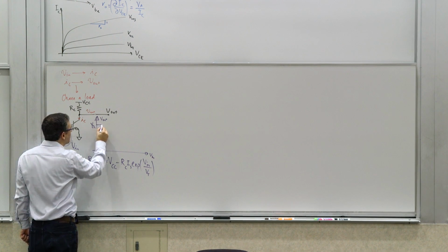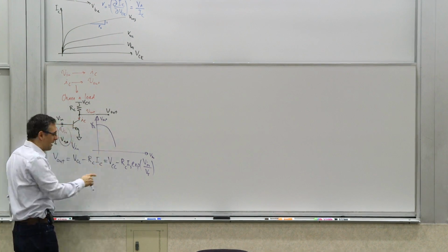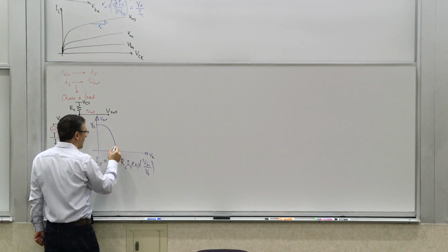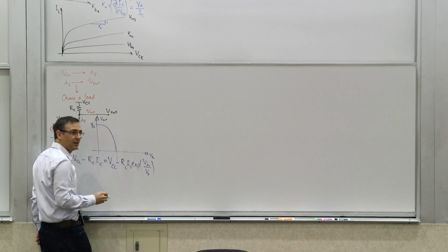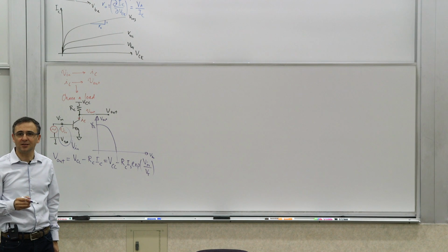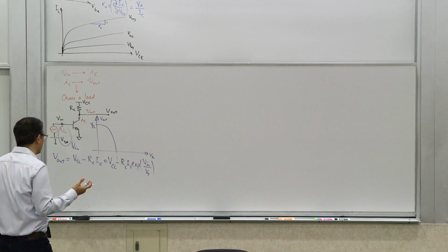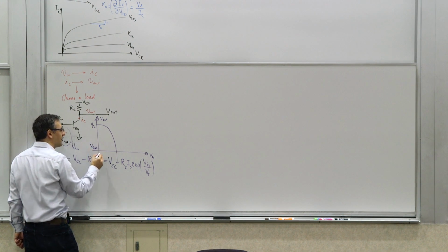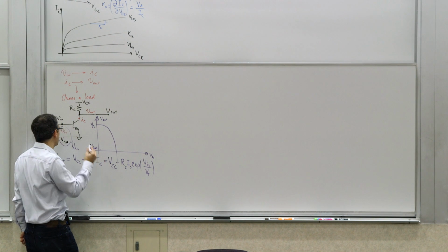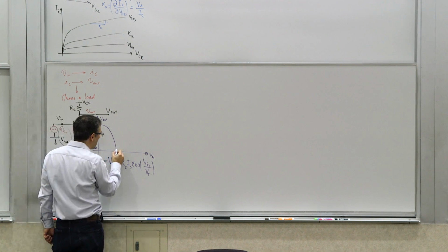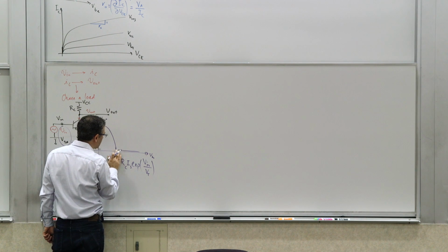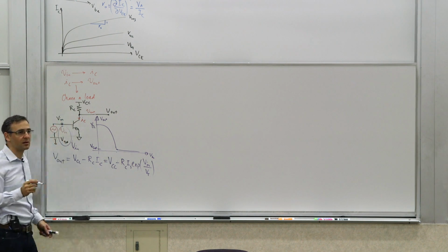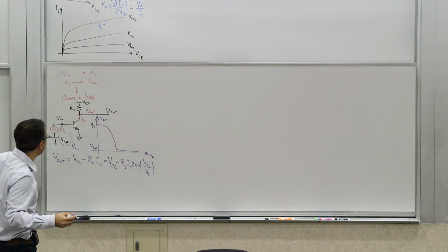As you increase Vin, you gradually have the exponential coming in and reducing this voltage. This term kicks in, and would it continue forever? No, something changes at some point. What is that? Once you get to a level which is like 0.1, 0.2 volts, the VSAT, then the transistor enters saturation. This junction is forward biased. Therefore, the actual characteristic would look like that. It's a more graceful transition, but regardless, it's something like that. So this is your V in, V out characteristic.